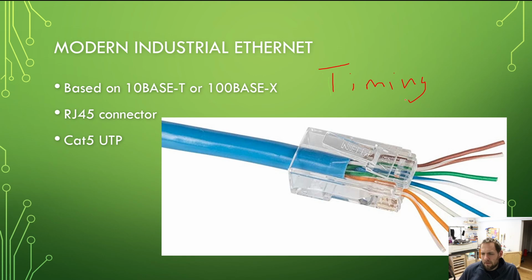So RJ45 for home use, and I'm really going to specify home use here, is a fine connection. It gives us 8 wires connected very reliably in the long run. However, when it comes to the ruggedness of this connector, it kind of sucks. I'm sure many of you have had this stupid retention clip right there break off on you. Now, if that breaks off, can you still use the connection? Yeah, you can still use it. There's no big issue about that. Nothing fancy going on. You can still slide it in. There's just nothing physically holding that connector into the plug anymore.